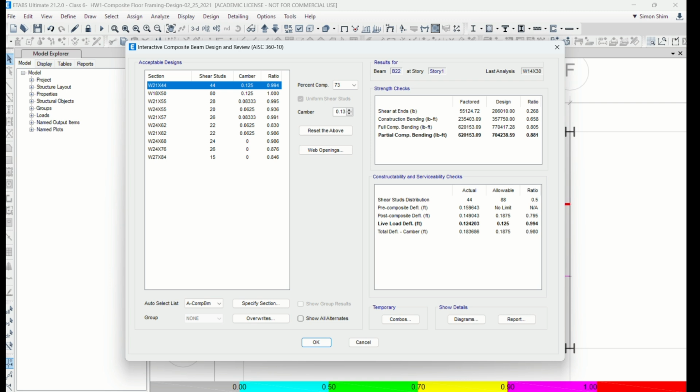Understand section modulus, right? That is your nominal, full plastic bending capacity of this section. It's simple. I just want you to at least understand this first one is during the construction phase, right? Only the steel contributes, but this steel beam should be strong enough to support this loading, which is the bending moment. The second one is obviously this factored moment, which is 1.2 dead, 1.6 live load combination with composite action.